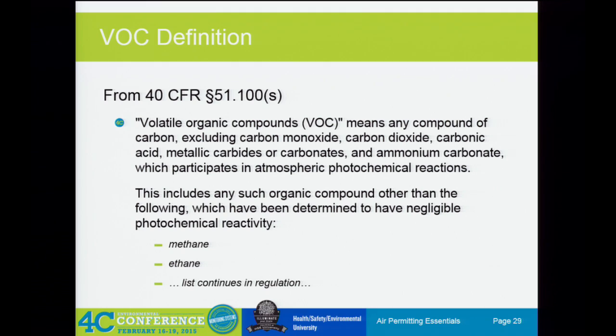It also includes any such organic compound other than the following, which have been determined to have negligible photochemical reactivity. So methane and ethane are a few of the specific ones that everybody is familiar with that are not considered to be VOCs. Another one that I see a lot of times that people confuse as being a VOC, which really isn't, is methyl acetate. But other than that, you can look at that list in the regulation to determine which specific hydrocarbons are not VOCs, but most of them are.